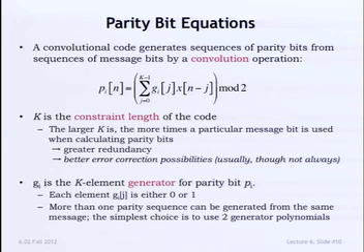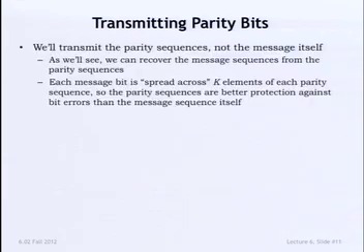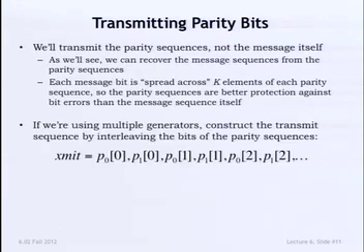This is not saying anything new, so how do we come to actually transmitting? Well, we generate the parity bits, and then, as I said, you send all the parity bits associated with your computation at time 0, then all the parity bits associated with the computation at time 1, time 2, and so on.